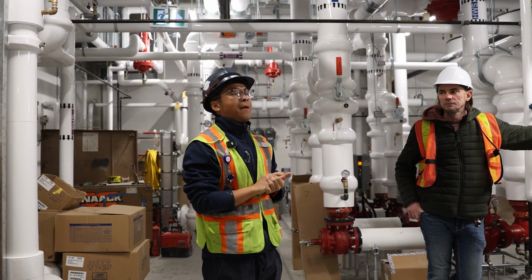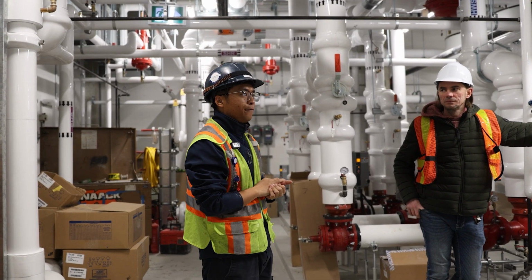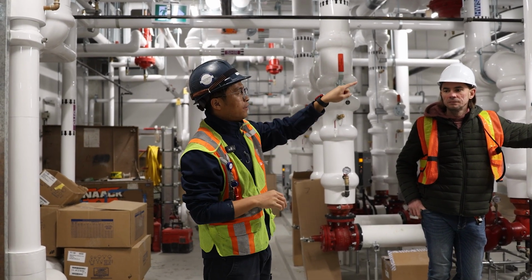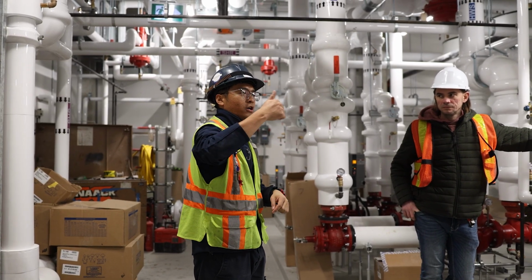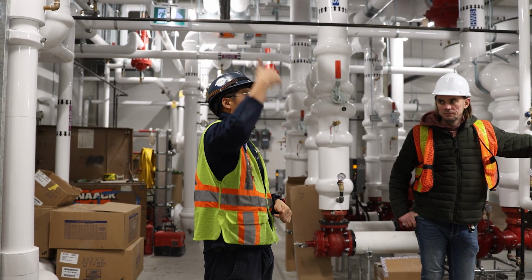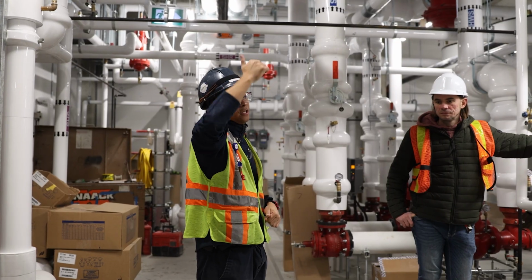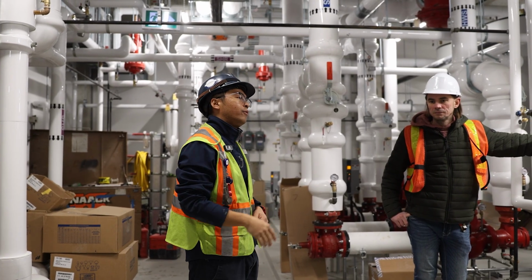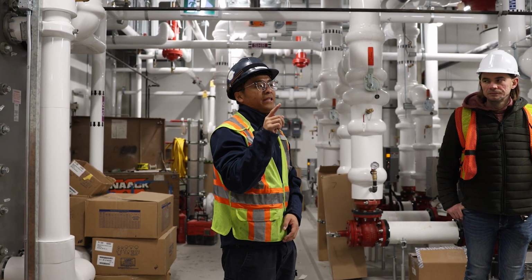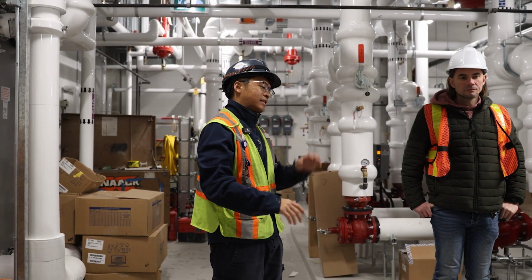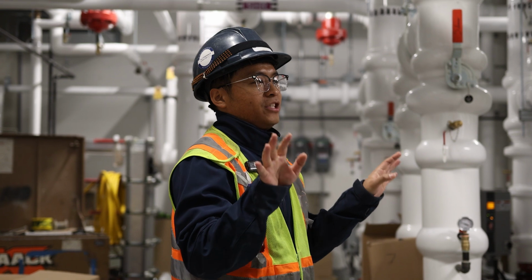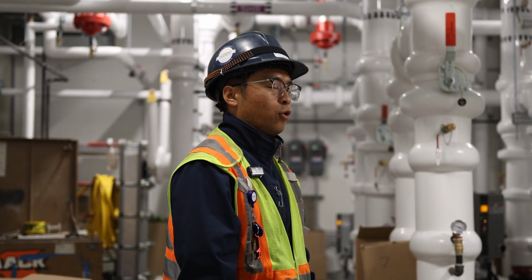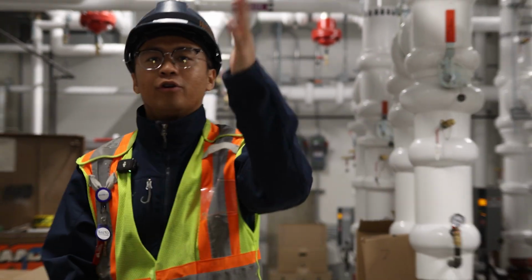I believe it's 52 degrees. So if the storage tank 1 and 2 temperature drops below 52, the boiler supply water temperature set point will increase to provide more heat to the loop. The boiler has an internal high limit. As long as the high limit reaches the set point, the boiler will be turned off. I can show you the boiler.